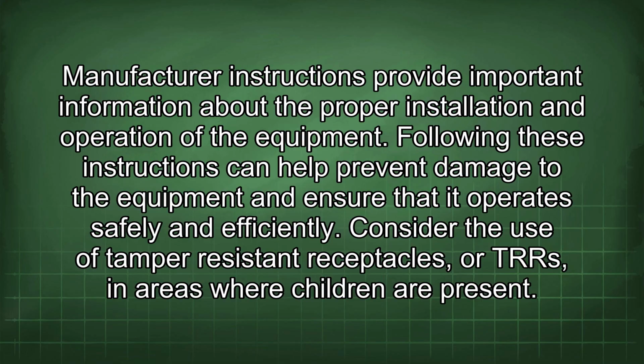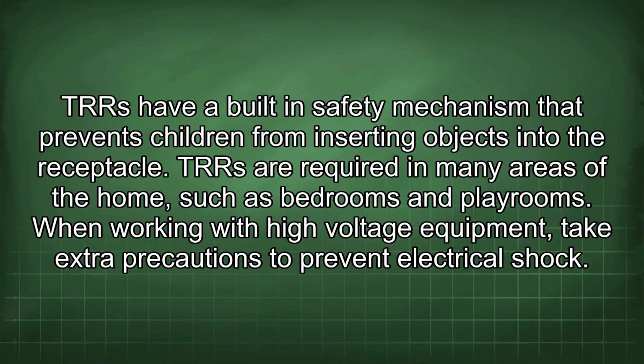Consider the use of tamper-resistant receptacles, or TRRs, in areas where children are present. TRR have a built-in safety mechanism that prevents children from inserting objects into the receptacle. TRR are required in many areas of the home, such as bedrooms and playrooms.